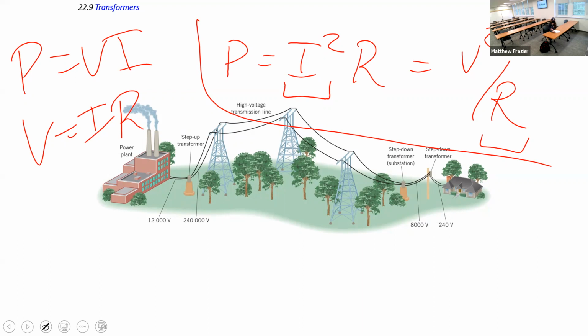Your voltage drop is measured as so many volts per mile, and it's a smaller number, so you can have a longer wire and have the same voltage drop. Does current also have that drop over distance? Generally not, because it has to be conserved. Whatever current starts in the line has to get out of the line somewhere.